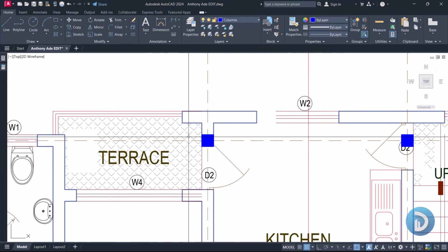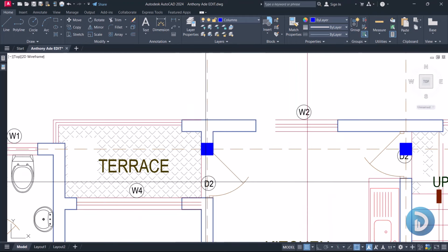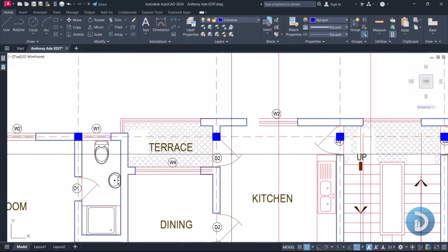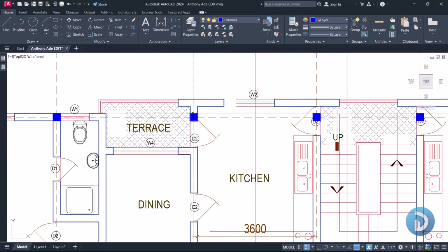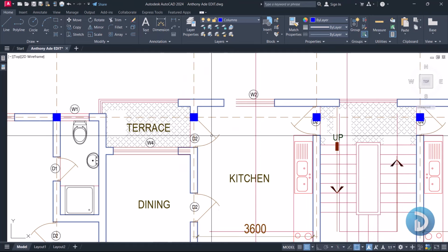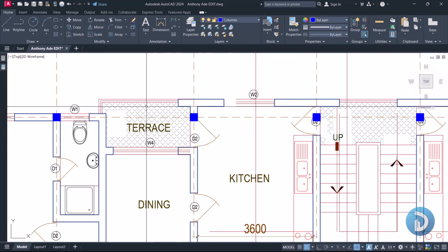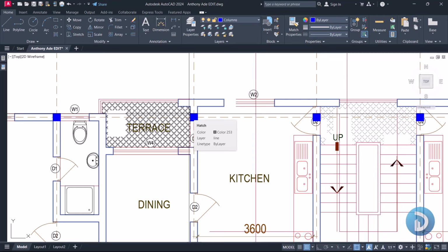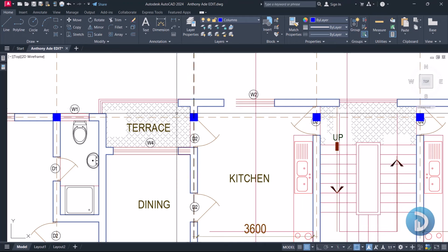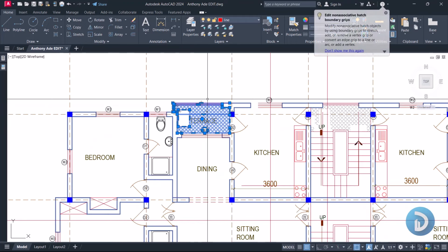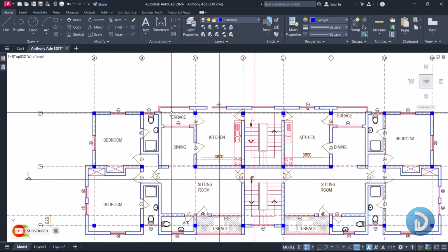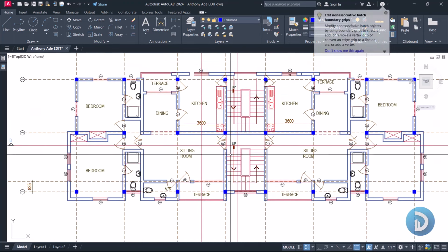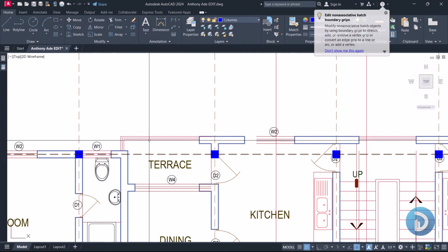Now moving on to grid line C, you will observe that we have an interaction between this column on grid line C and our door over here. So if we continue this from the ground floor up to the first floor, this will interact with this passage, the passage door here to the terrace. So we'll make modifications to this in order to suit this current arrangement that is occurring on the first floor. And this is as a result of this cantilever. Okay, let's erase this as well. So this is as a result of this additional cantilevered part.